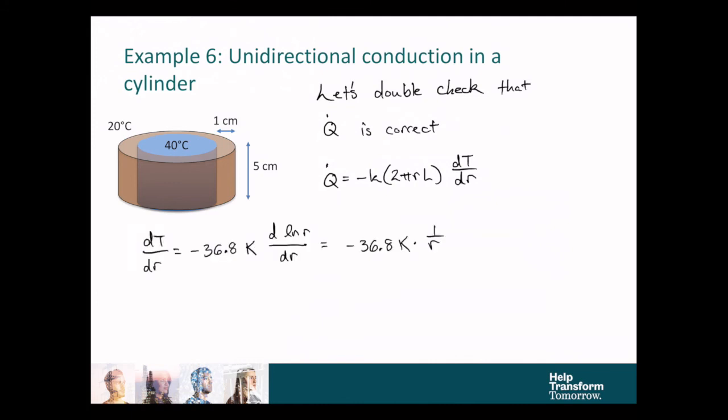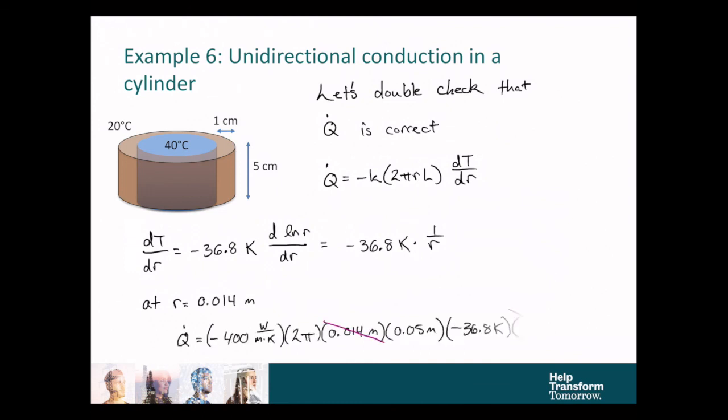So let's differentiate it and double check that we get back the heat flux we calculated in the first part. So if you differentiate the temperature profile, you get a constant and an inverse r dependence. And we'll just choose any r value. It should work for every potential value within the thickness of this copper shell that we choose.